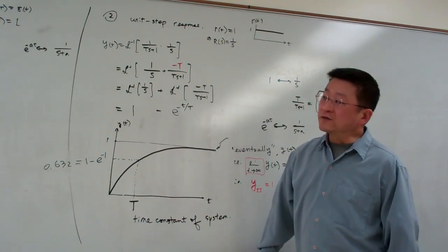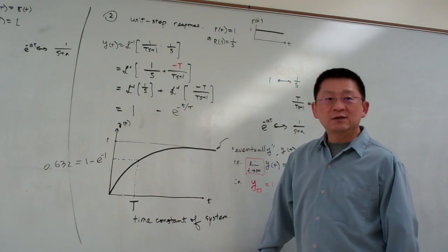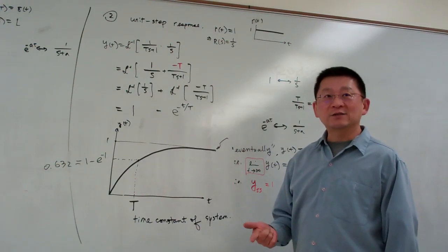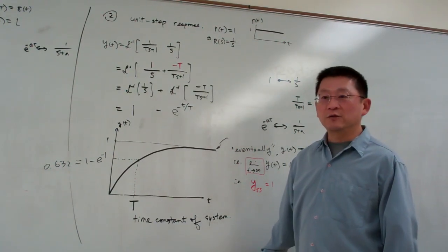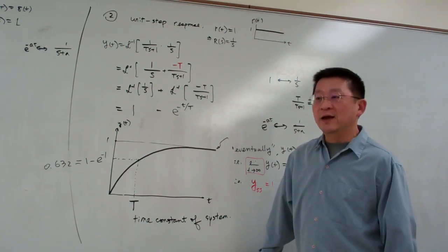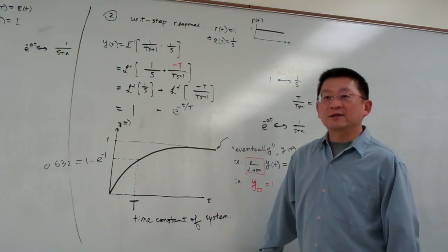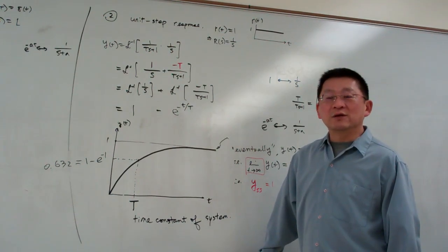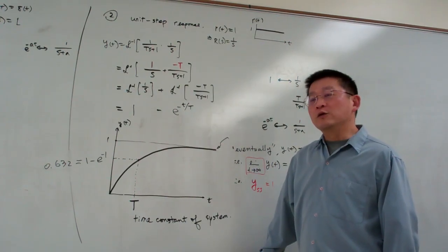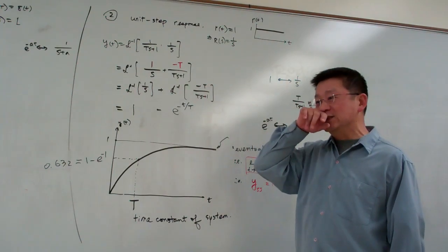For most electronic systems, if you design an RC circuit, with resistors and capacitors, they will come up as a first order system. Those kinds of electronics have a time constant usually measured in microseconds or less. If you remember, or you have even taken instrumentation, you can see it immediately from an oscilloscope.